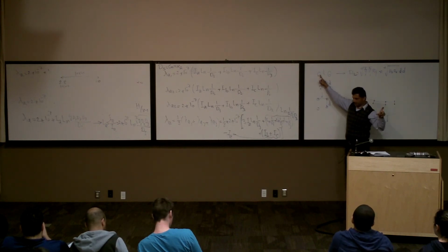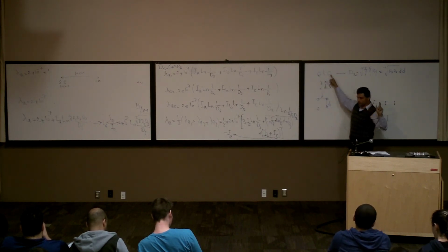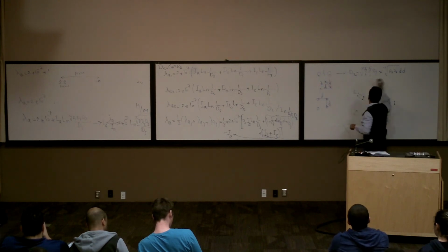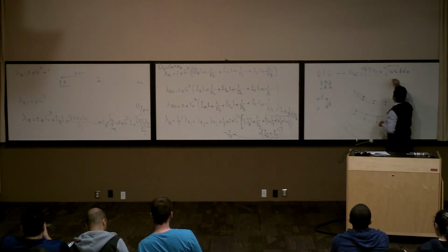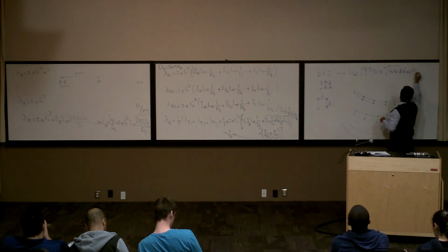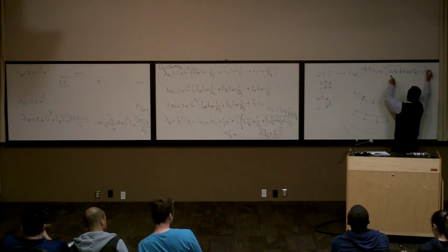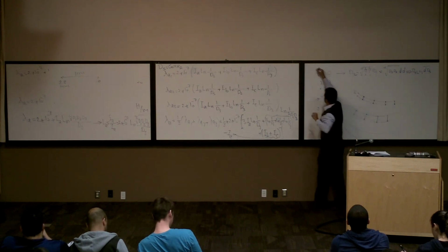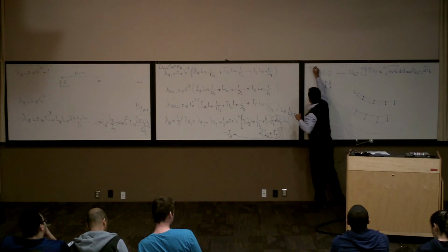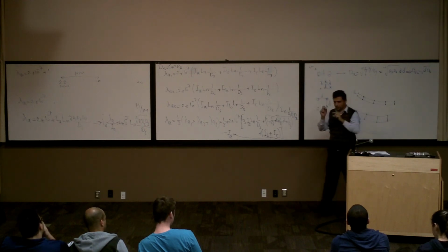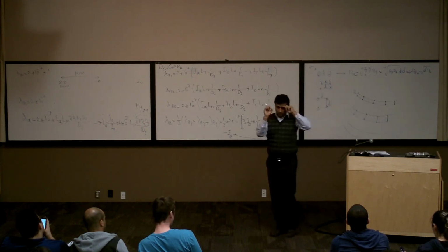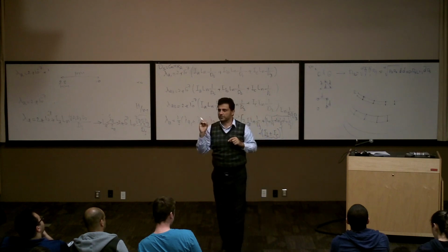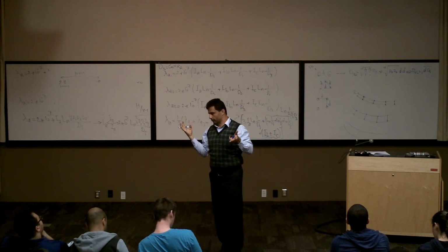We said you use a DS to show that. How much is this one? DS again, right? So basically DSL is going to be D, DS. DS is the GMR of each conductor. We call it DS or R prime. If it's a single conductor, DS is R prime, right?